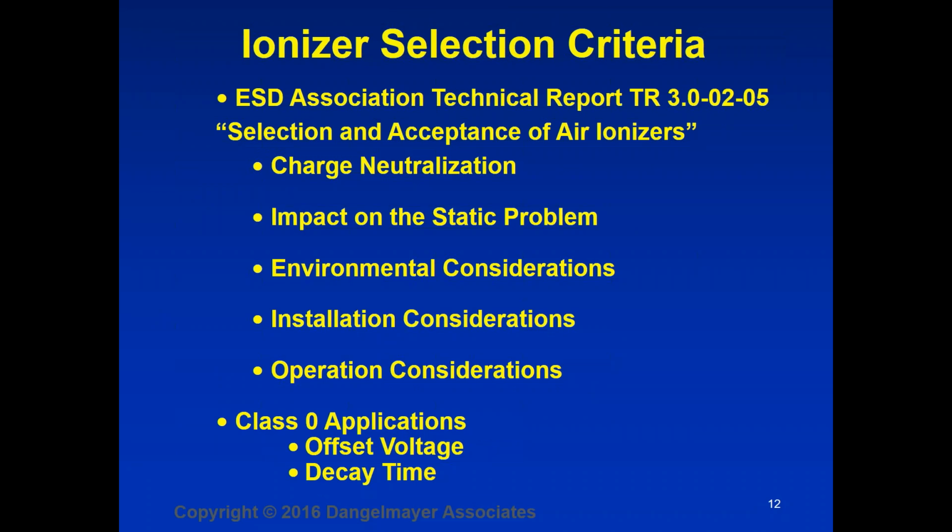So how do we select an ionizer? Fortunately, there is some data available that helps you with this process. You see the ESD Association technical report, TR 3.0, mentioned there, and it's called Selection and Acceptance of Air Ionizers. And it deals with the topics we have below there. Obviously, in selecting an air ionizer, you need to know what its charge neutralization conditions are, and we'll talk about how you measure those later in the webinar.